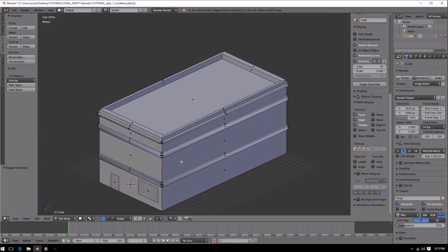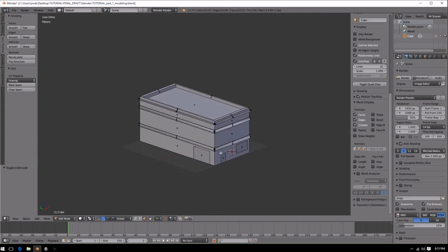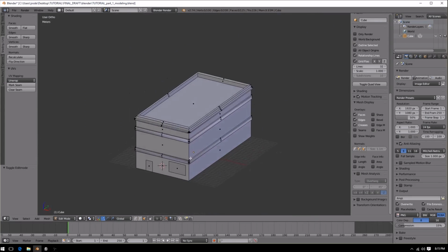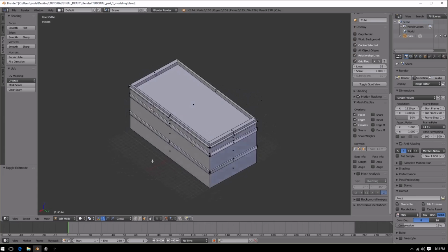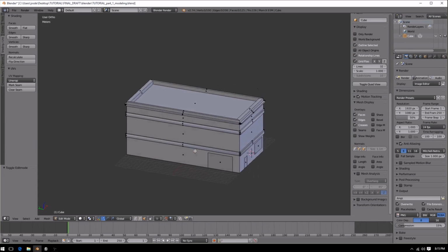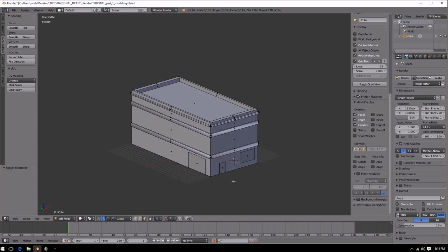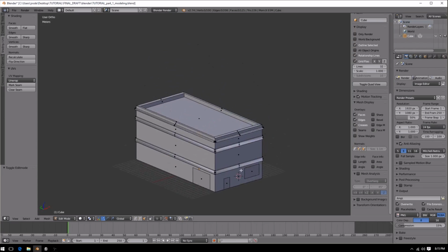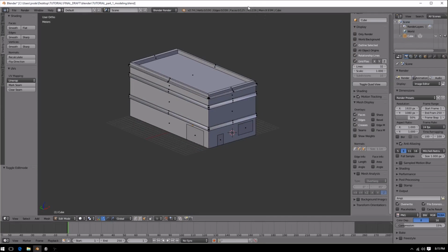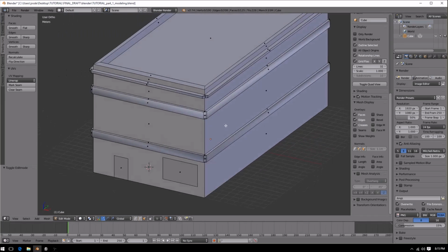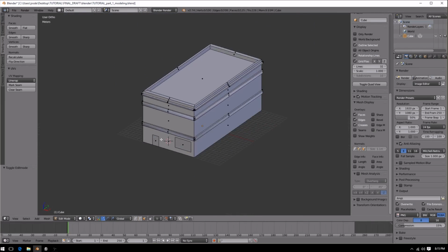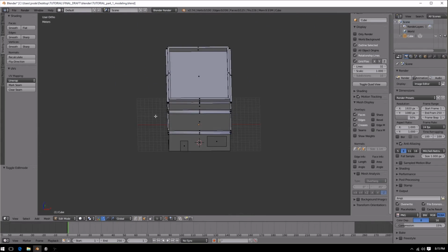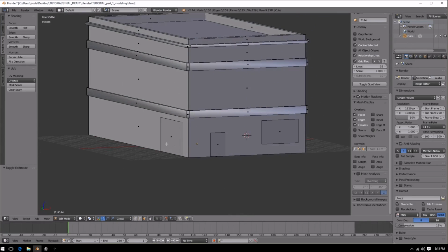And I'm kind of a bad modeler anyway, so eventually they maybe don't look exactly as professional as they could be, but I figure with as many assets as people want to use, it's best to try to keep these numbers down, and to always be mindful of that. If you need to use tris and make geometry and spend detail and there's no other choice, then that's what you got to do, but think about everything you can to try to avoid using geometry if you can.